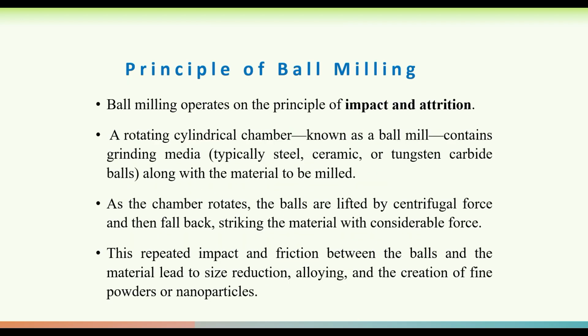The principle behind this ball milling technique is that it operates on impact and attrition. Attrition is nothing but friction or pressure that we are creating. So, we will take a rotating cylindrical chamber, known as a ball mill, that contains grinding media. That grinding media is typically steel, ceramic or tungsten carbide balls. Along with this grinding media, the material which we want to grind is also taken in that cylindrical